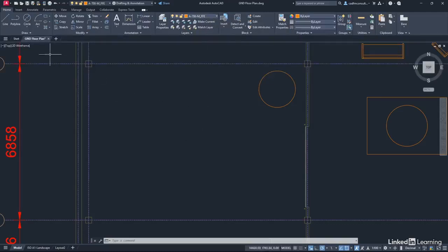We're now going to go up to the Draw panel on the Home tab on the ribbon and click on Polyline. Come into the drawing area, pick a point sort of there-ish. It doesn't have to be exact, but about there, and left-click once. Using your polar tracking, you're going to drag to the right and type in 3500, which was the length of the horizontal side of the table we've just erased. Press enter. Now, that's the first segment of our polyline.